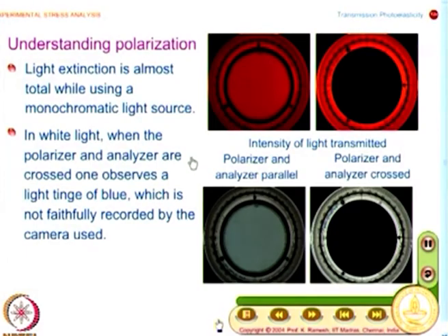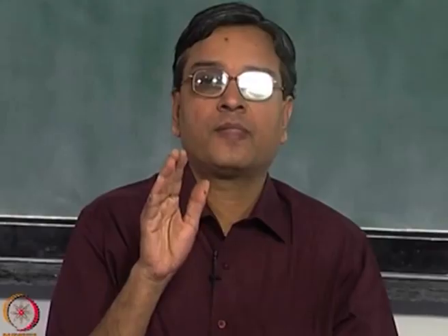So, what you have learned today is what a natural light source is. Before that, we looked at light as a sensor in photoelasticity, and we wanted a mathematical description. We recognized light is an electromagnetic disturbance with electric and magnetic vectors, and for convenience we will always represent the electric vector as the light vector, with the implicit understanding that a magnetic vector is always perpendicular to it. They are mutually perpendicular, and we will have a similar situation with the ordinary and extraordinary ray later. You should not confuse that issue with electromagnetic disturbance.